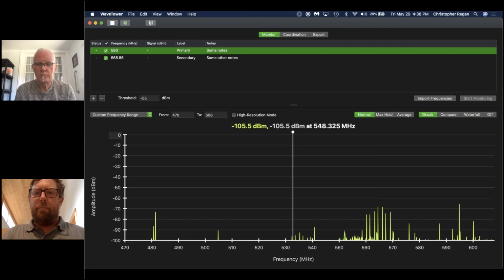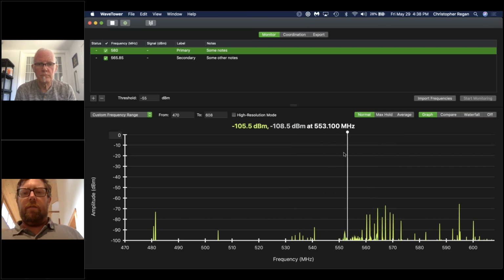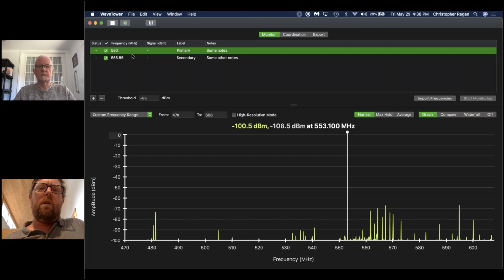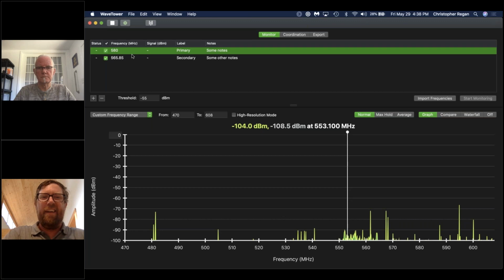And what that'll do is drop a marker at the position, and it'll give you a red, yellow, green readout of what the signal level is against a threshold that you set. So for doing a live show or commissioning an installed system before you hand it off, it's a really good way to test out and understand where we're at. Do we need to move antennas? Do we have enough signal in the area where we need it?